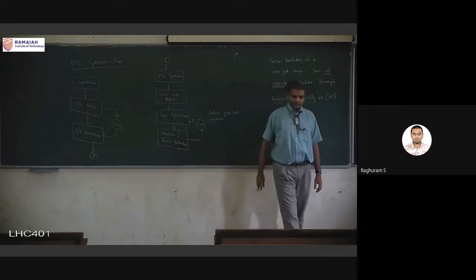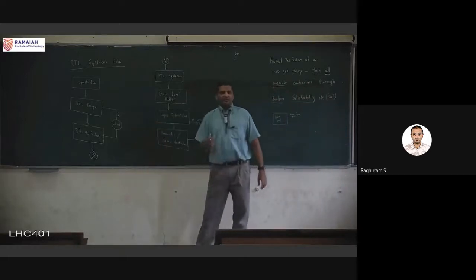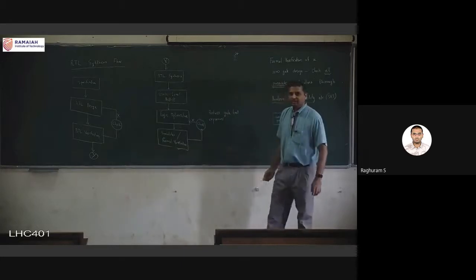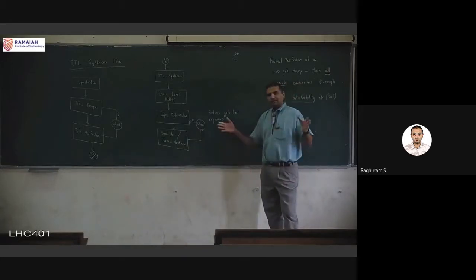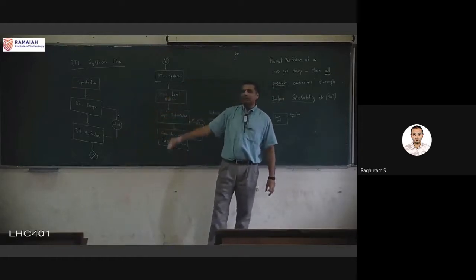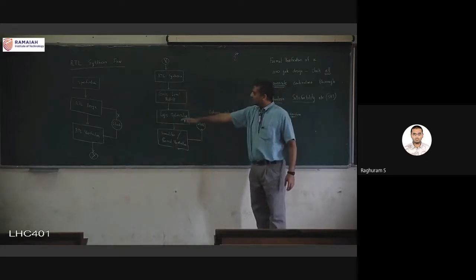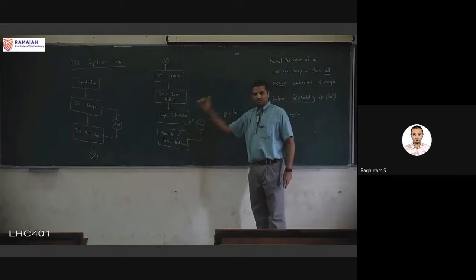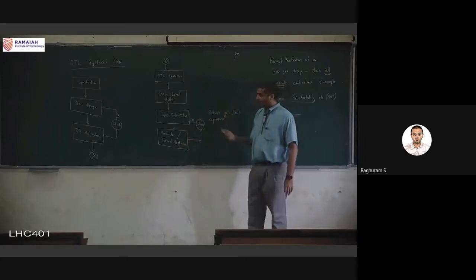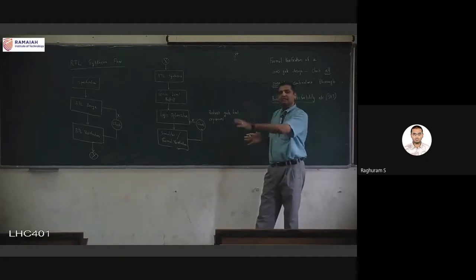Another interesting aspect of this whole VLSI design: we see these checks a lot, right? And I said that the checks are for when some error is happening, so it may require some manual intervention. In the overall VLSI design flow, 70% of the time goes to the verification steps. After every design step there is a verification step: RTL design, RTL verification, gate level netlist, logic optimization, then simulation or formal verification. Similarly, in every step, there will be a verification step. So in the overall design flow, 70% of my time is going for verification. Only 30% is the actual design step.